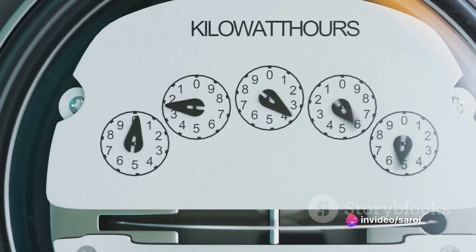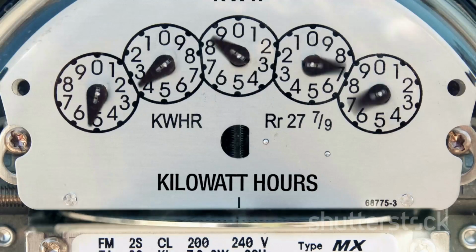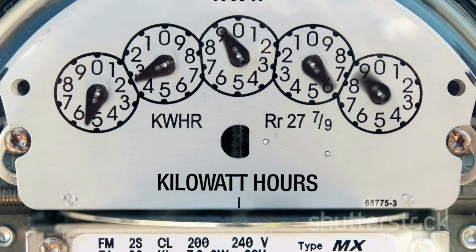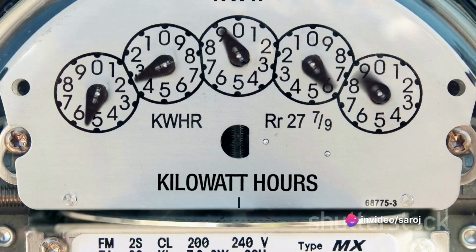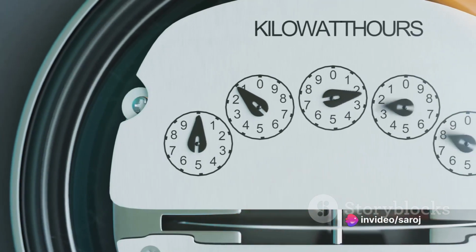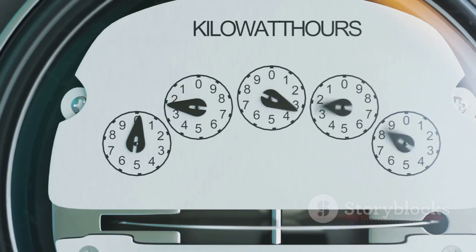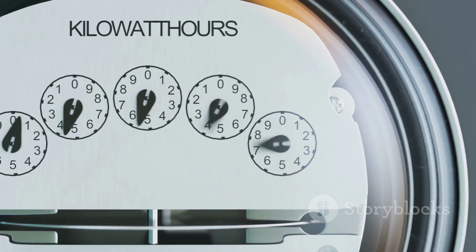Now, energy is a term that's thrown around quite a bit. But what does it really mean in the context of electricity? Simply put, energy is the total amount of work done or potential to do work. It's measured in watt-hours or joules. Let's break it down. A watt-hour is the amount of energy consumed when 1 watt of power is used for 1 hour.